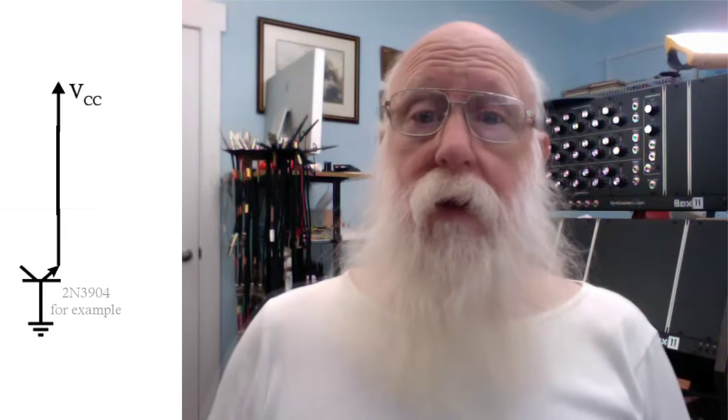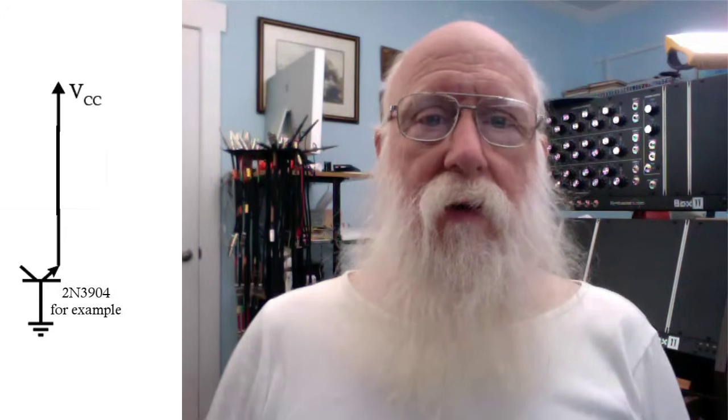To look at a basic circuit for generating this signal, usually you will probably use a transistor instead of a diode. They typically will generate a better noise signal. And it doesn't matter whether you use PNP or NPN, and you can test different ones and see which ones give you the best noise signal. But here I'm using an NPN. And remember, we need to do something to limit the current, so I will put a resistor from our positive supply, plus 15 volts, to the emitter of the transistor, and then I'll ground the base. The collector is simply not used. We're only using the emitter to base junction.